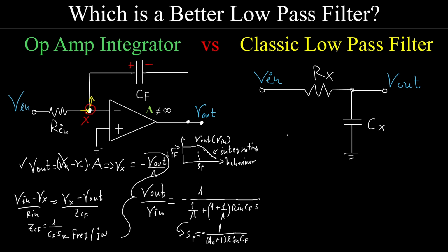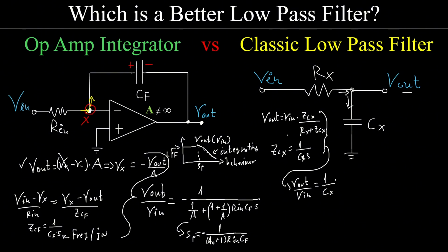Alright, now for the classic low-pass filter, how much is the voltage here at Vout? Well, this is nothing but a typical voltage divider because the current comes inside here and then goes downwards over here. The current is the same, this terminal is common for Vout and Vin. This is a typical voltage divider from circuit theory. Again, how much is the impedance of the capacitor? And if we do the math, this will be the output over the input, and from here we can find the pole, which will be equal to...